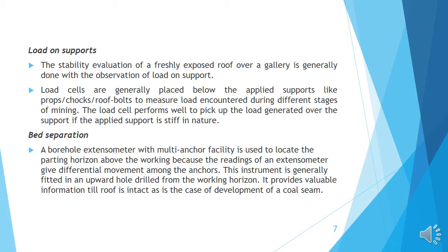Now the bed separation. A borehole extensometer with multi-anchor facility is used to locate the parting horizons. This instrument is generally fitted in an upward hole drilled from the working horizons. It provides valuable information while the roof is intact and in the case of development of caving.